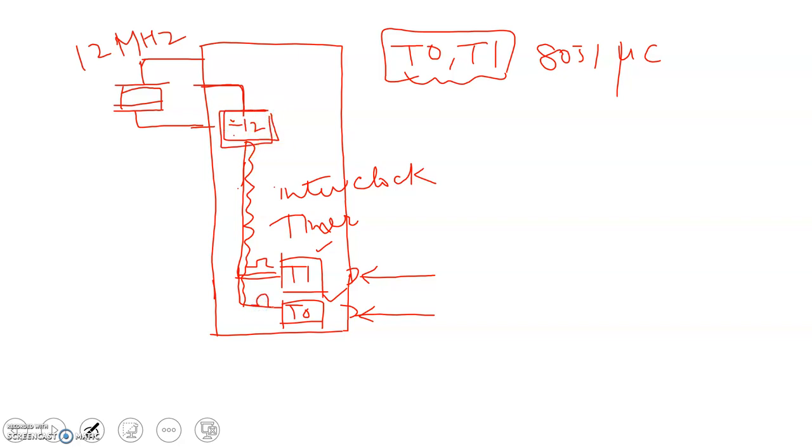Similarly for timer 0. While if we intend to use the 8051 in counter mode, then we have to use the external pins, and basically it is an event counter wherein the frequency of the pulses that are coming is not fixed.